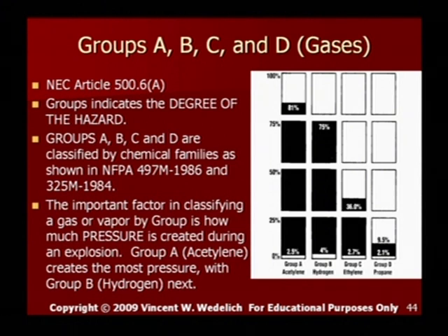There's some arguments about, can you take an area all the way to a general purpose area, and that's a little harder to do, because what if the mechanical device fails? Then you have, again, a Div 1 location. So typically with a mechanical ventilation device, a Div 1 area is allowed to be a Div 2 area, but not a general purpose area.